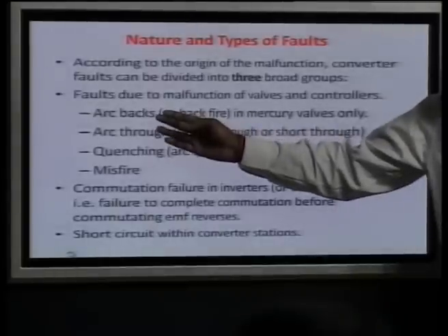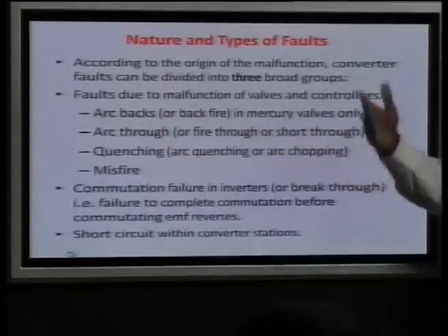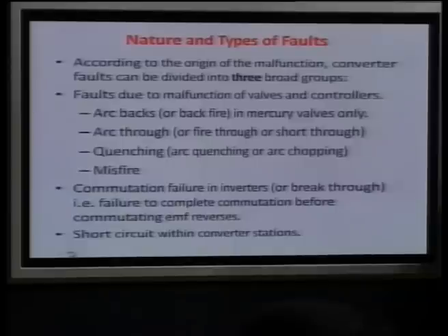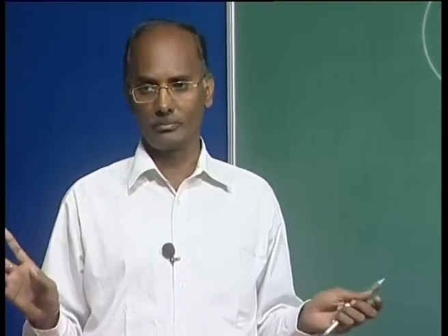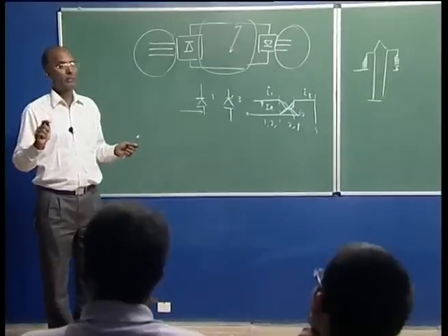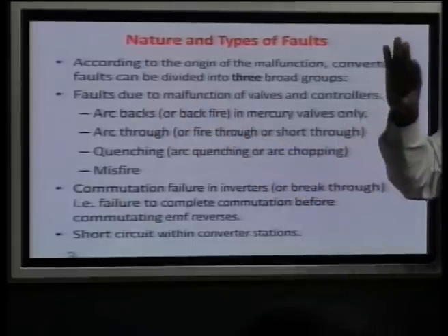It is conduction when the voltage across the valve is negative. Normally in a thyristor, if the voltage across the valve is negative and you are giving the gate pulse, it will not conduct in any case. But in the mercury arc valves, it was possible that even in the negative polarity they were able to conduct. So, that was only at that time, the old stages.